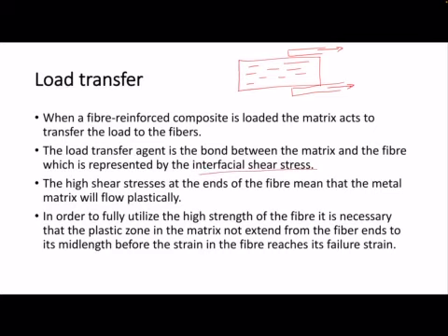So interfacial shear stress would be, if this is your fiber, maybe that shear stress, and there's your matrix all around it. So the interfacial shear stress is that along the outer surface of your fiber.